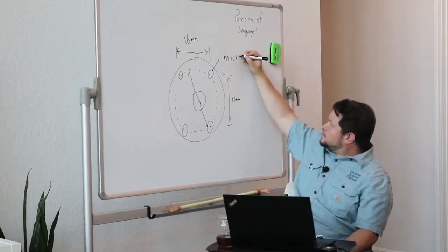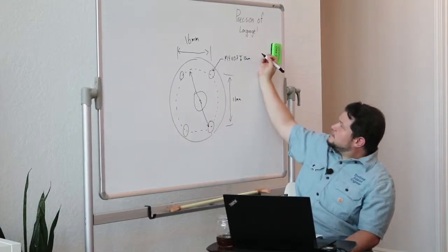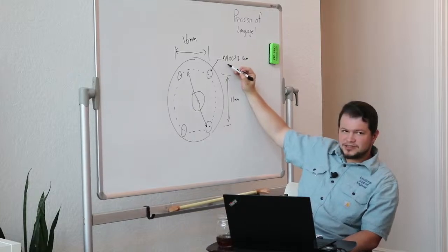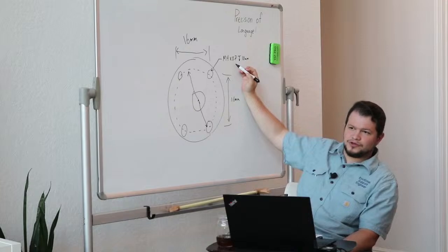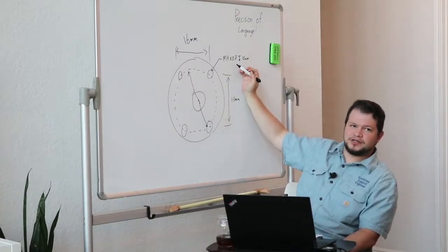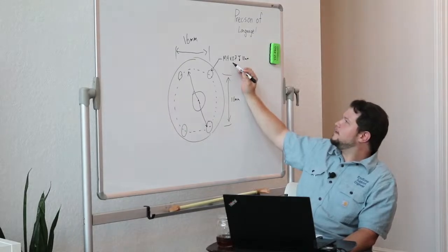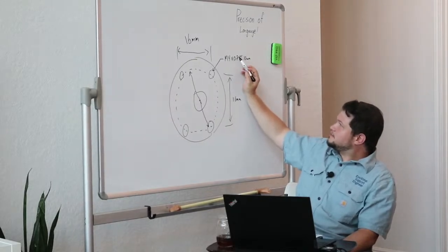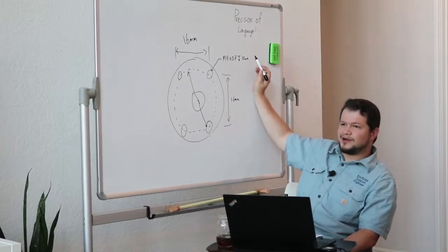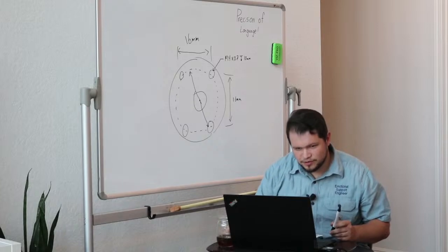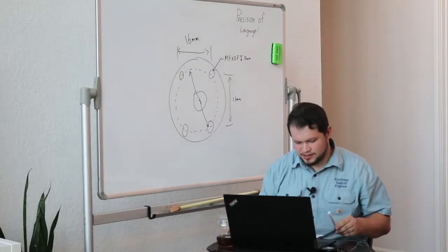So typically you'll see something like this. M4 is the size of the screw. This is the thread pitch. Very rarely will you use a fine thread metric. Almost always it's going to be what's called coarse thread. So this is the size, and then this is the depth of that hole that you have threads to work with. So we're going to go back to our part file, and I've put points in here.